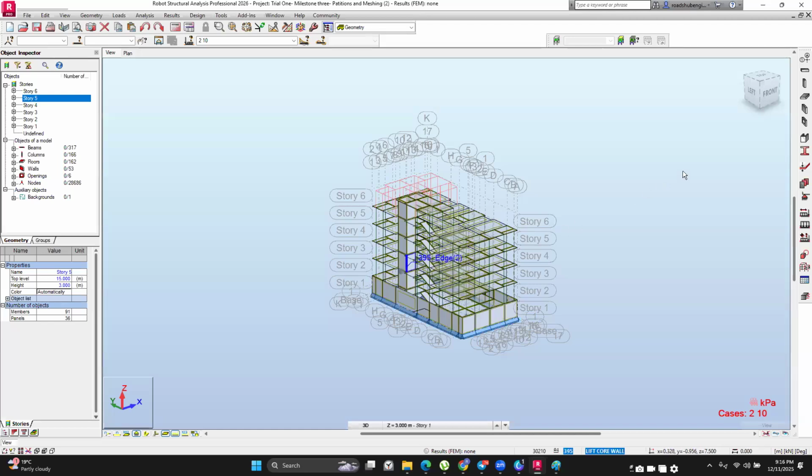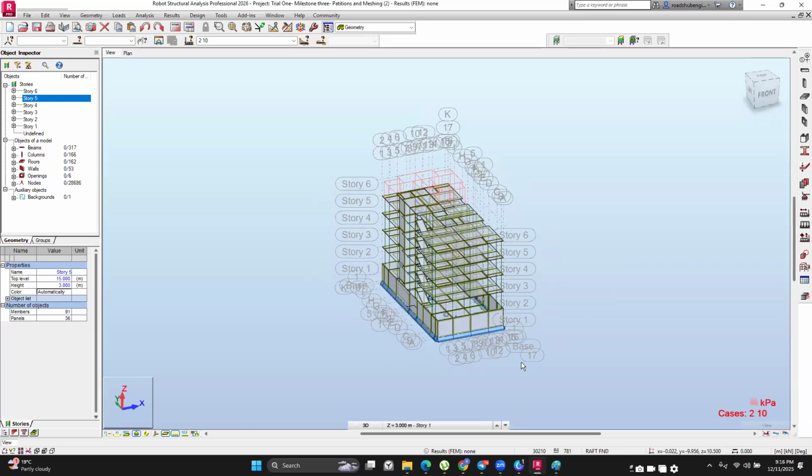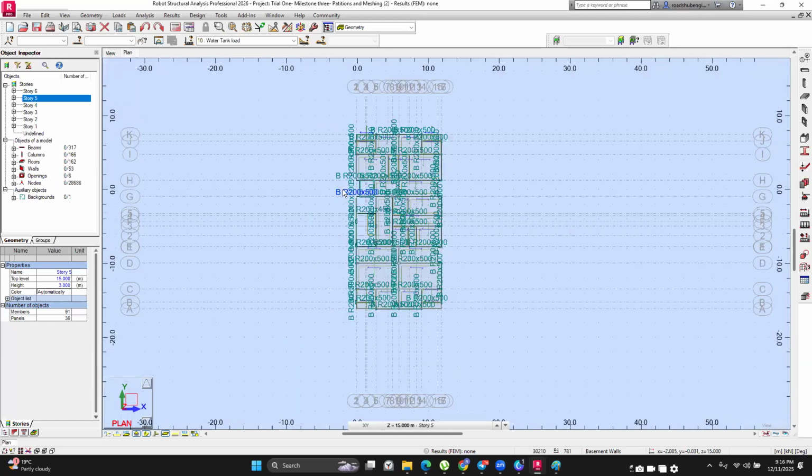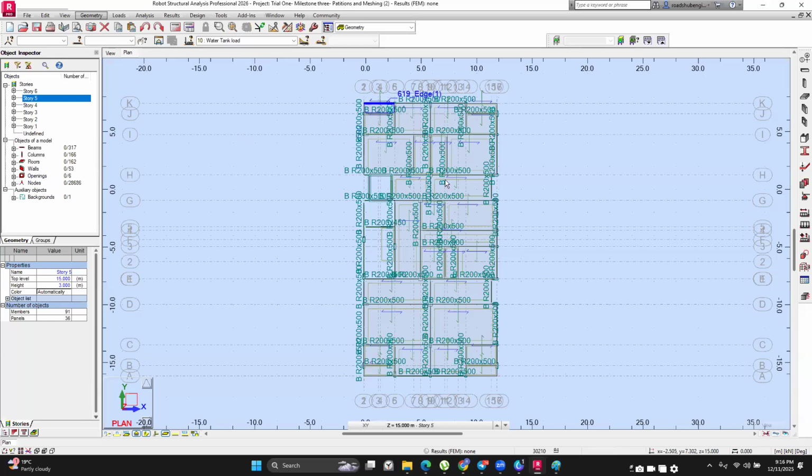The reason we are doing this is because you are only going to be using it for wind simulation. And we said you only need to do that in two adjacent directions. So this one, and we can do one in the orthogonal direction here. So let's do that. This one should be simple. Let me zoom in. So we are going to be working with cladding, and this is important. Please don't model a panel, model a cladding. The cladding does not have any weight, and it's not going to affect your analysis.